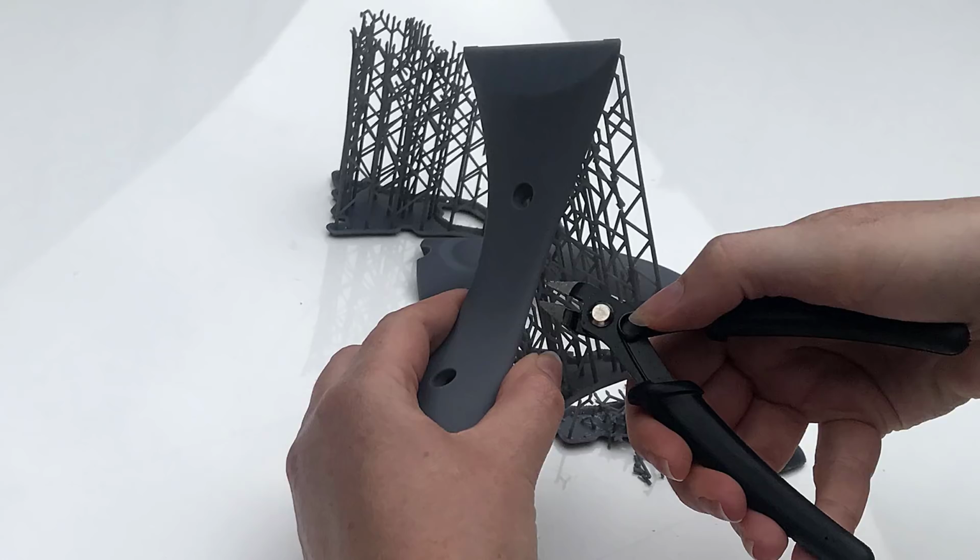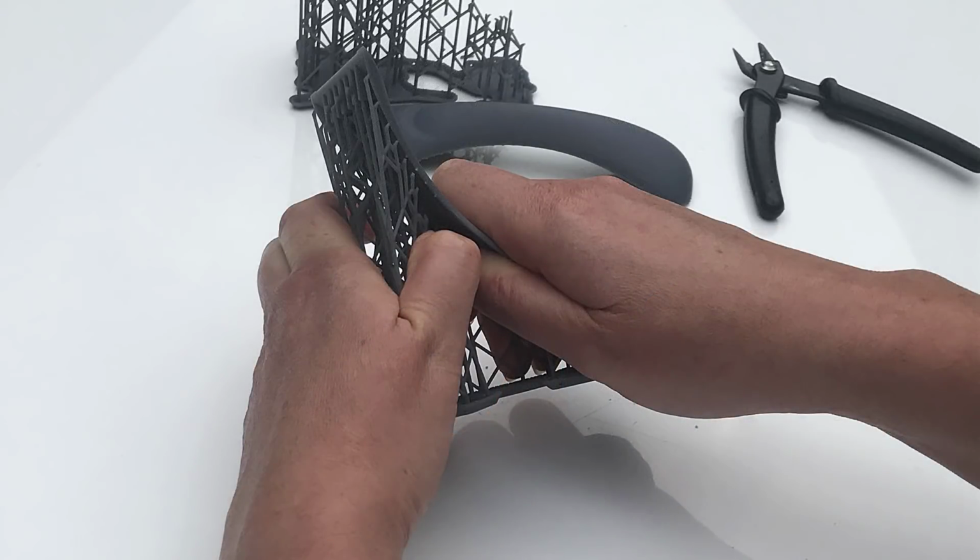Here you can see Steph, our Formlabs certified technician, cutting through the top of the supports with needle nose cutters. The main supports are sometimes called scaffolding, and the cross section of the scaffolding reduces where the support meets the part at an area known as the tip. In many cases, once the first few tips have been cut, the remaining supports can be broken away.